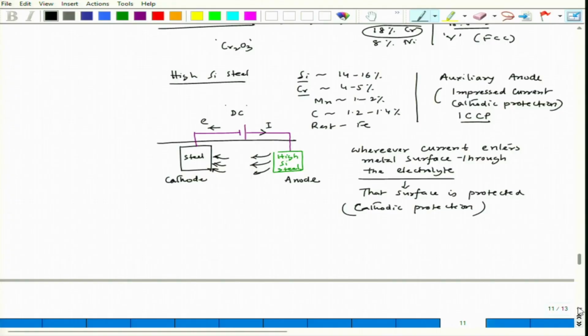but the graphite problem is it is very brittle. So, while operating, while handling it during installation, if it breaks, then the purpose is lost. So, the material for this particular case should be strong enough, at the same time it should not have quite a lot of dissolution, that means the self dissolution tendency should be as minimum as possible. So, that is why we designed it this way. So, now you see the effect of compositions.